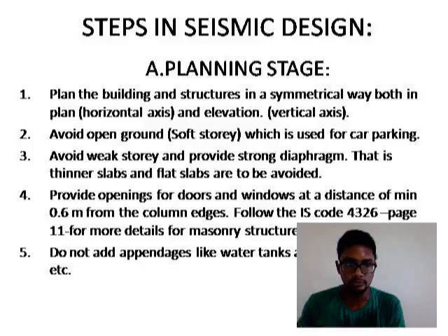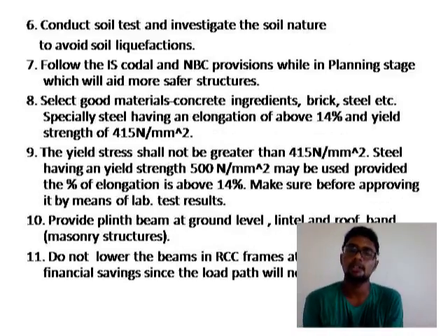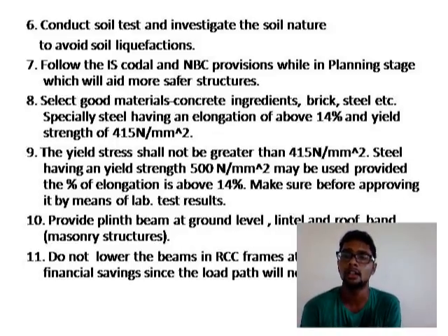And going to the next slide, soil test. A soil test has to be initially performed before the construction of an earthquake-resistant building, because based upon the soil, the foundation will vary. If the soil is clay, pile foundation is mostly preferred. And following the IS code, IS 1893 is mostly seen for design of earthquake resistant structures.